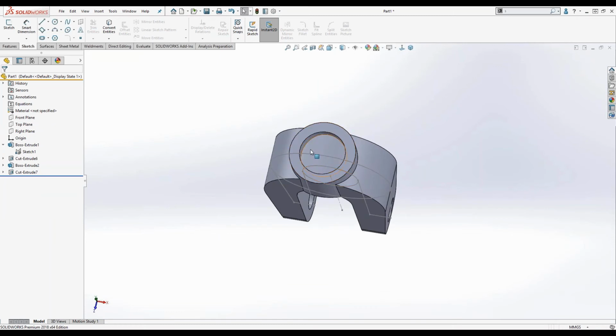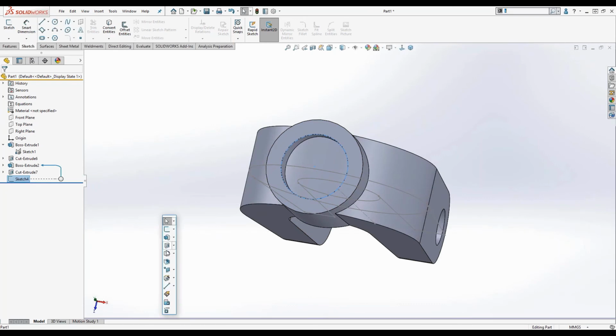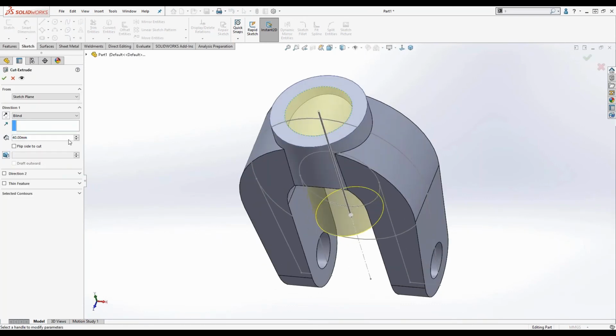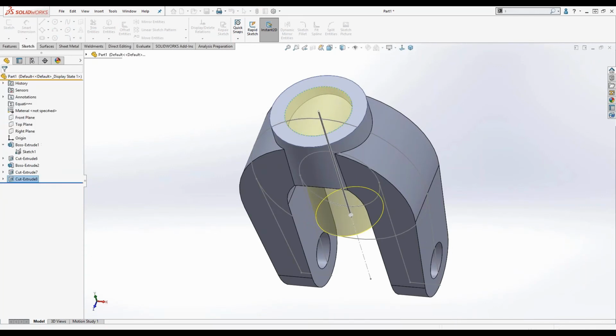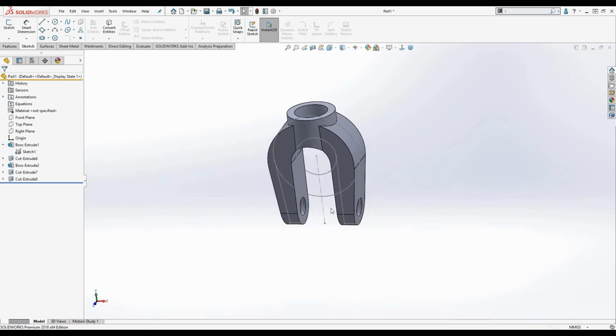The other thing I want to do is make a cut through all here. I need this boss to have a hole in the center. So I'm going to utilize my breadcrumbs, do a sketch. I'm going to do a convert entities. I'm going to utilize that sketch. There we go. That's what we wanted. Now the blind or through all in this case, I don't really care. I'm just going to hit the D key and check out of it. Okay, so there's our completed part.